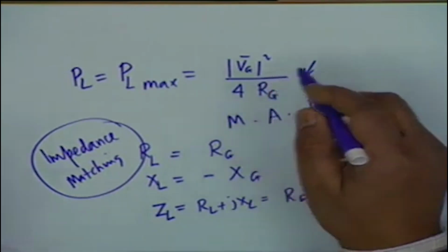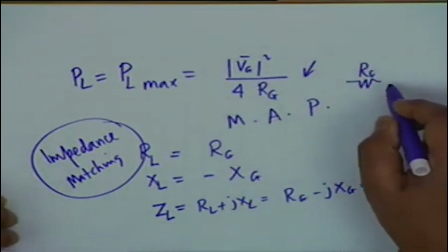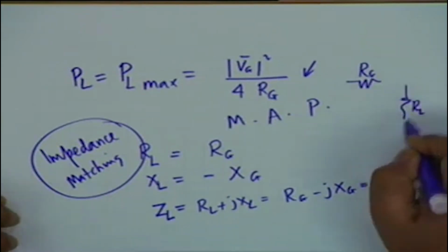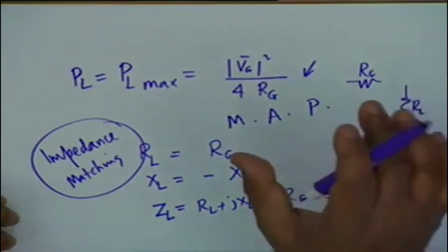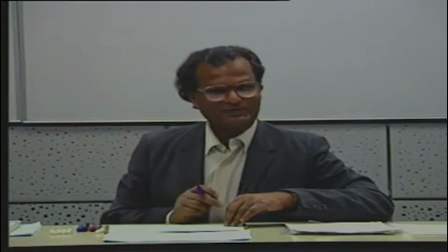Isn't that right? You see, the source delivers through a resistance to a load RL. And when the load and source are matched, that is, one is the complex conjugate of the other, RL absorbs this amount of power. This amount of power must then be absorbed by Rg also. So half of the power is wasted in the source.